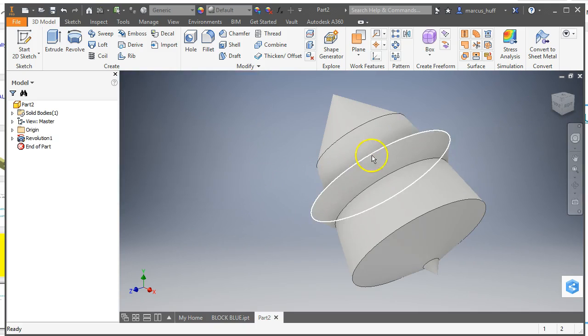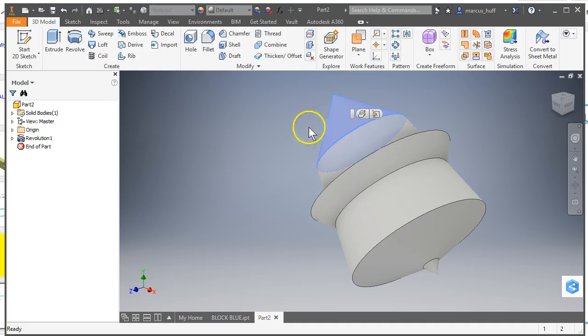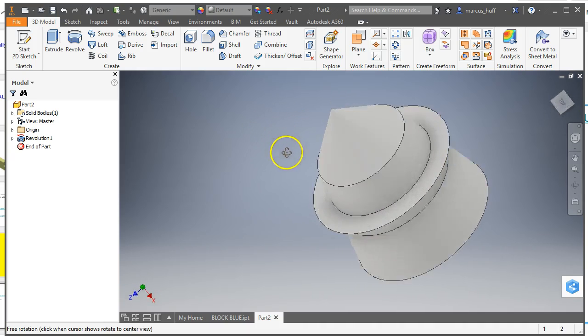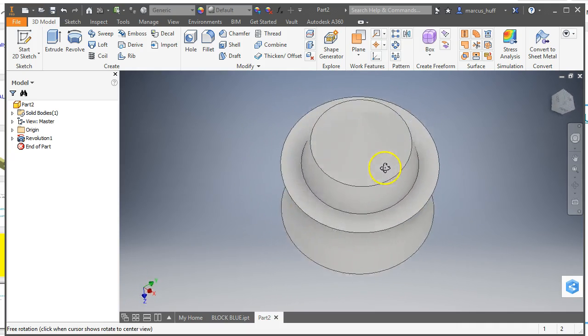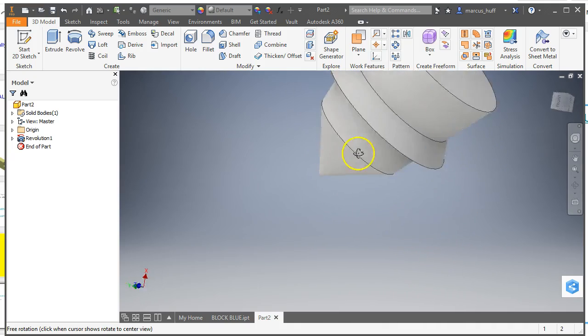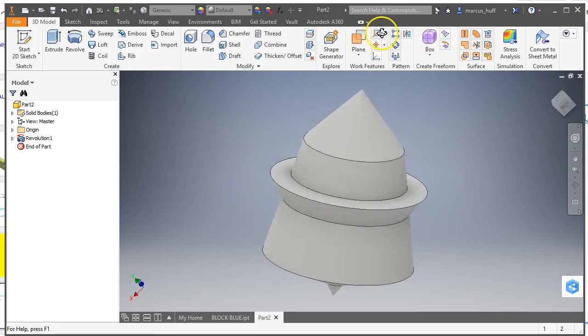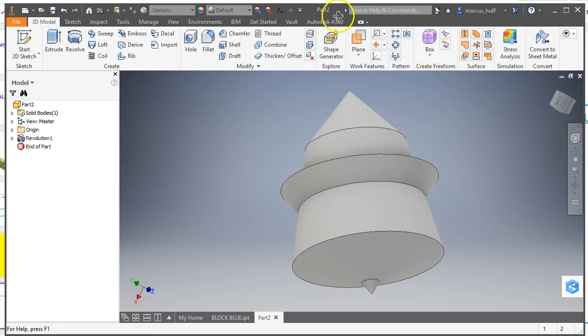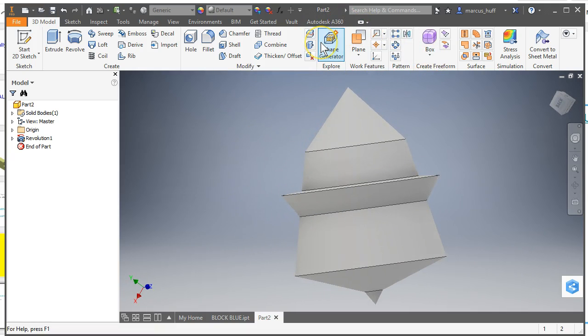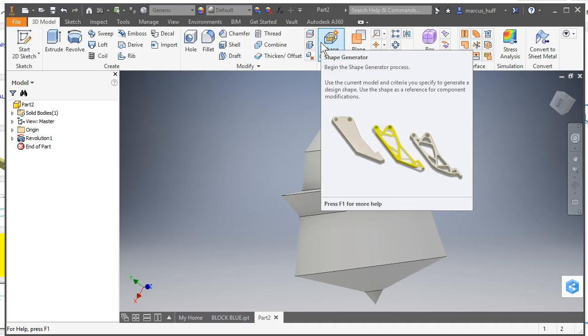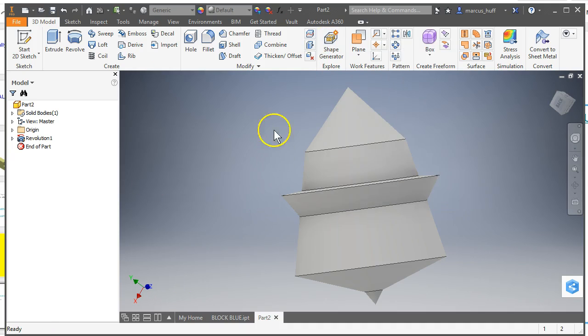So now we can hold down our Shift and center button, and we can view that in lots of different shapes there. If you want to make it look like a donut, you have to add a line to the side of your drawing and use that as your profile for revolution. We'll demonstrate that later. Okay.